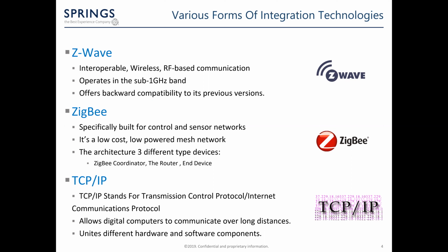The coordinator is responsible for handling and storing the information while performing transmitting and receiving data operations. Zigbee routers act as intermediary devices and permit data to pass to and through them to other devices. End devices have limited functionality to communicate with the parent nodes.